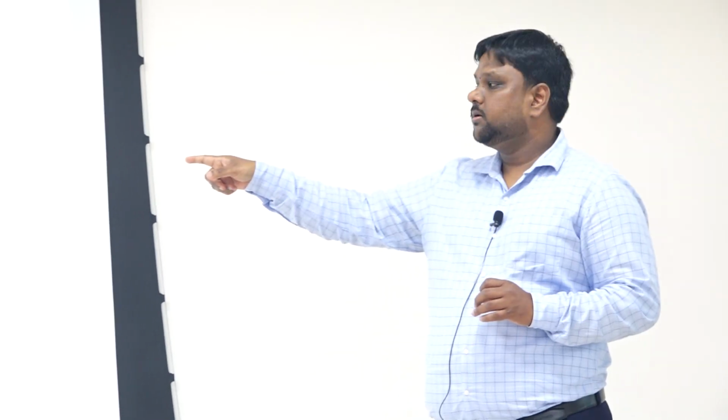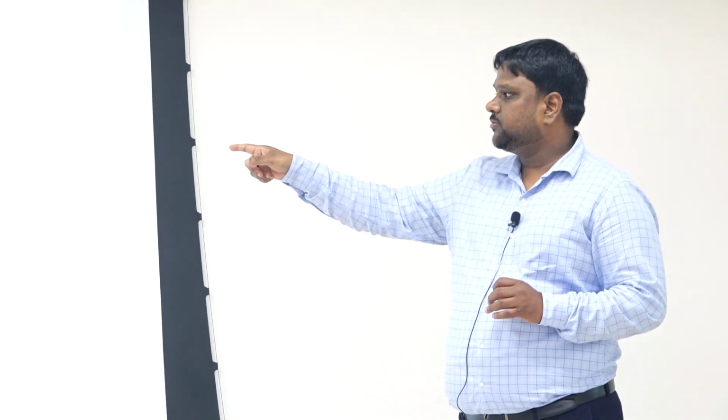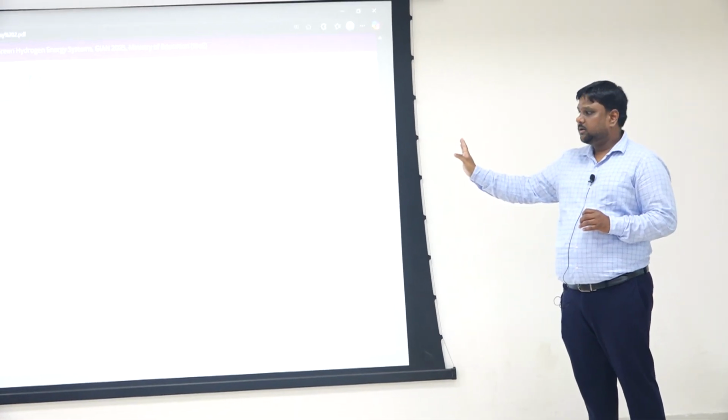Okay. I will show some of the controllers. As a conventional one, I already showed you. Let us say I tell about integral sliding mode control. Again, if you see my sliding surface, I am taking S of t as Ka times the error plus Kb times the integral from 0 to t of the error dt. Using that sliding surface, my final control law is this.